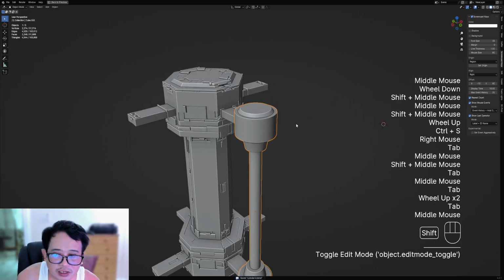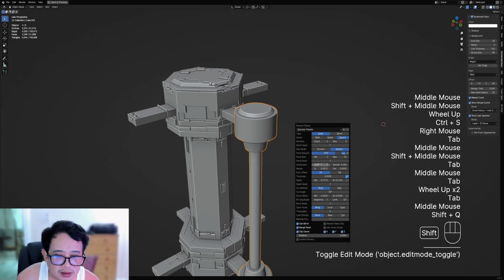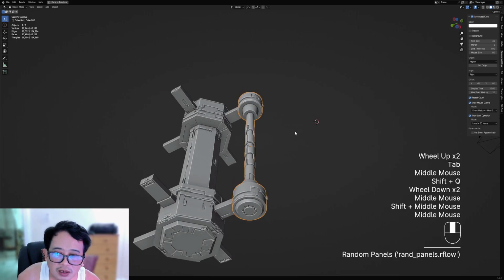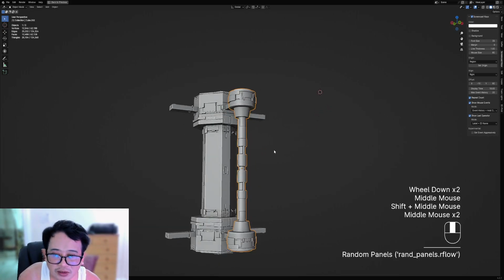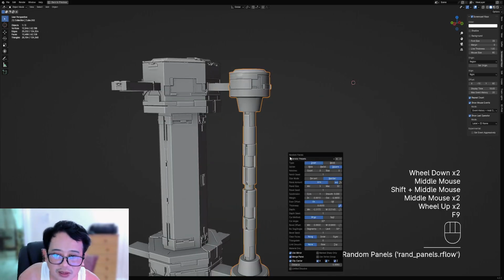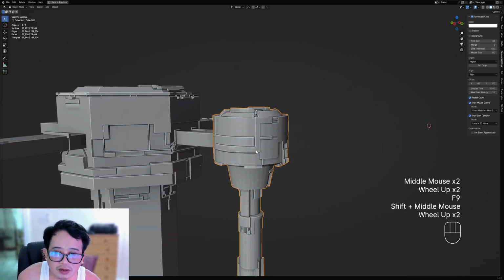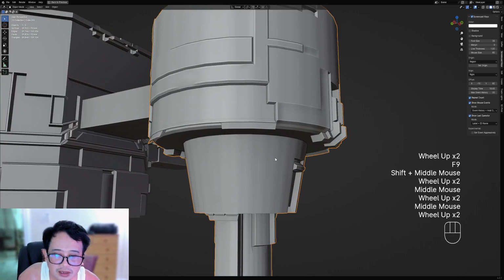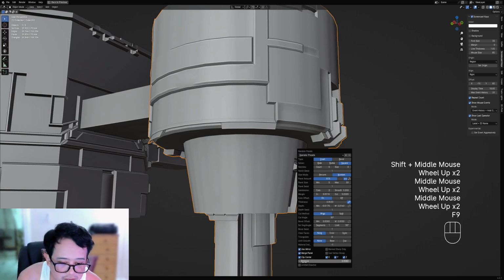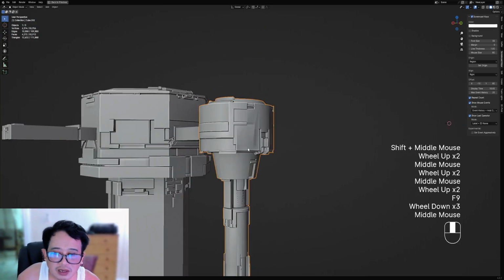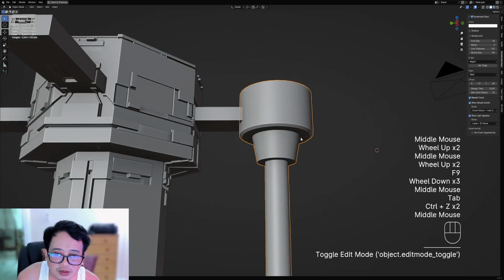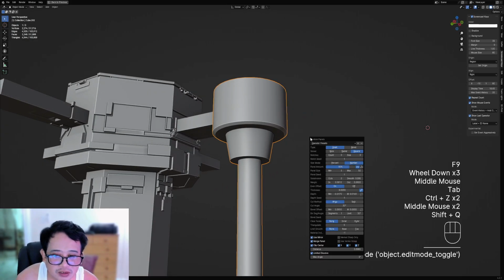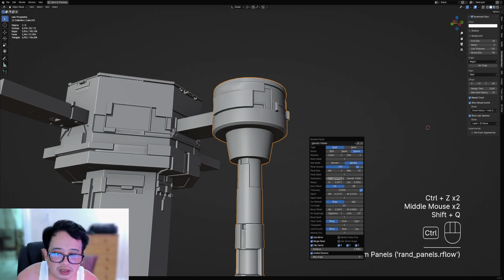So to be quick, let's just avoid using the partition operator and quickly get to it. So you can see the subdivision level 2 already gives you the banding. You can get rid of that using limited dissolve, but you get rid of the quad structure. So if you want to keep the quad structure, you need to limit your subdivision cuts to 1, even using cylindrical shapes.